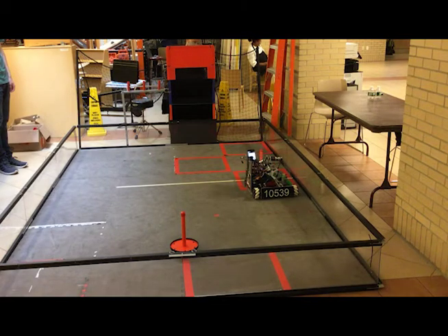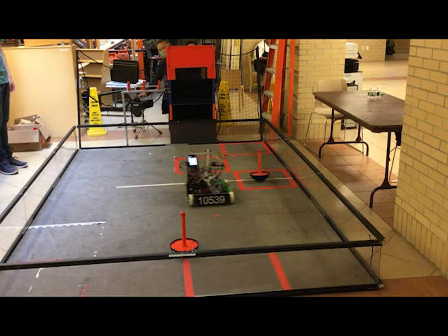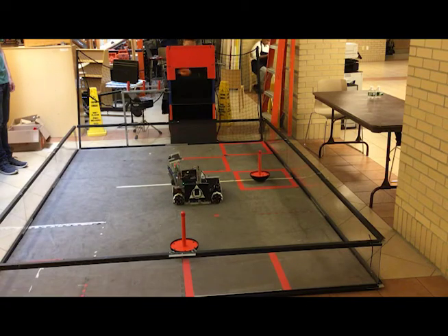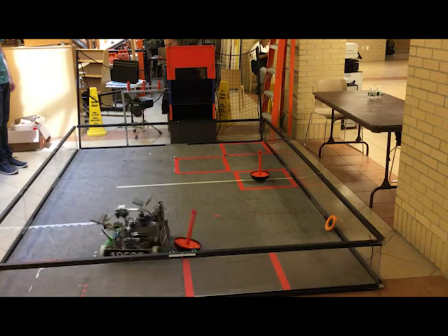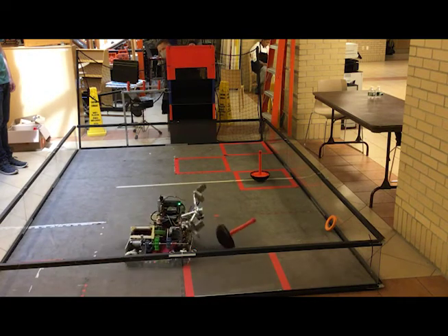We chose to install physical odometry pods on our robot, which are simply freely spinning omni wheels connected to an encoder that measure the distance our robot travels. There are 2 of them on our robot, one that measures the distance the robot drives in line with its wheels, the y-axis, and another that measures the distance the robot drives while strafing, in the x-axis.